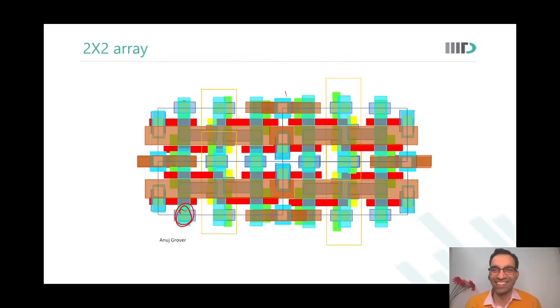Okay, sir. Understood. So whenever a new process node is defined, let us say I want to define the 3 nanometer process node now, the yield is actually ramped up on SRAMs. SRAM yield is determined, measured and tracked to see how the process has evolved, because SRAMs push the technology limits there. Understood. Anything else?